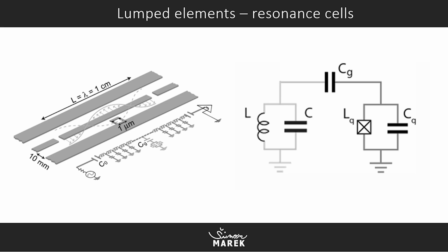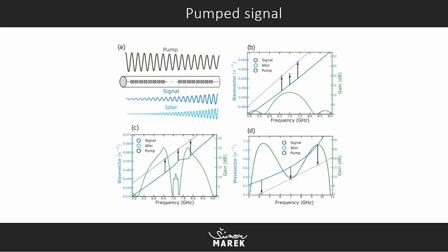The only difference is that this is a representation for a coplanar waveguide, and in our case we will use coplanar waveguides plus elements like real inductor shapes, and for capacitors we will use planes, because we will need higher values for capacitors.